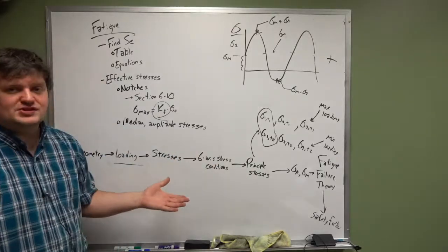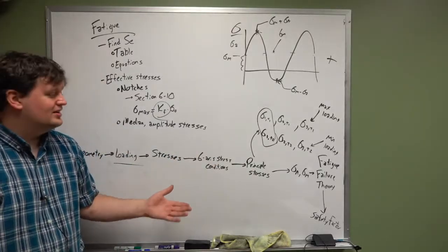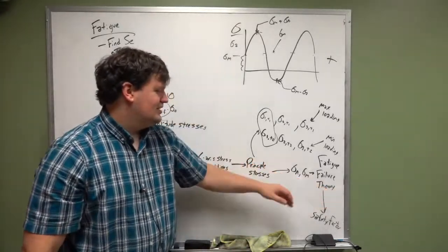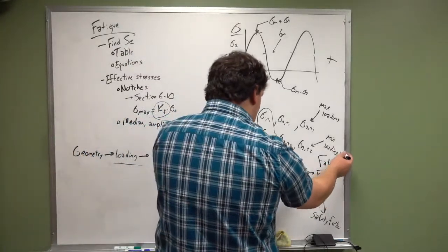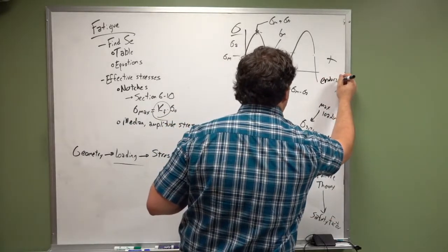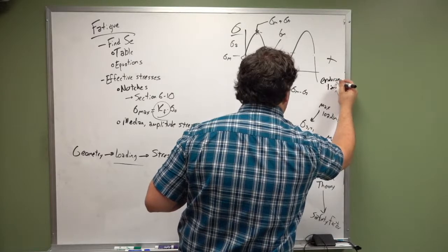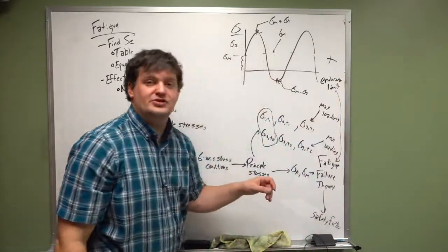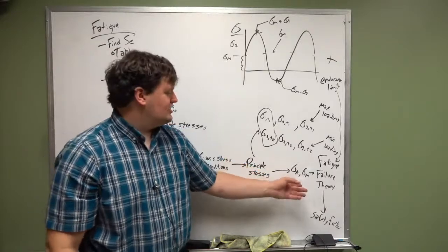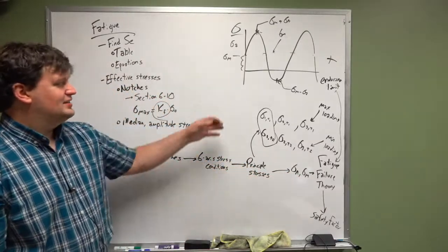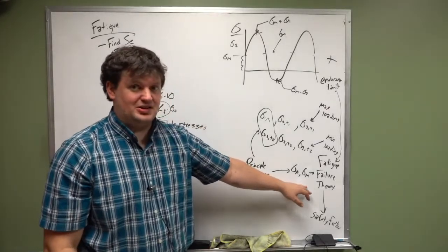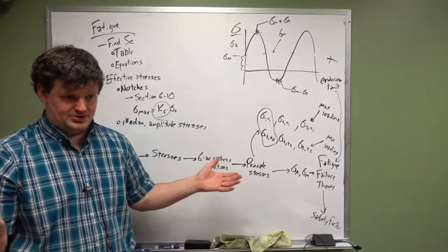We've added a few steps from static theory, but really the only thing we've added is we changed this from static theory, which means we do have to find what the endurance limit is. By the way, endurance limit, that's a step we had to add for fatigue. We now had to add this step also for fatigue, and you'll notice that sigma M, sigma A, again for fully reversed loading, sigma M is equal to 0 and sigma A is equal to the amplitude of the stress.